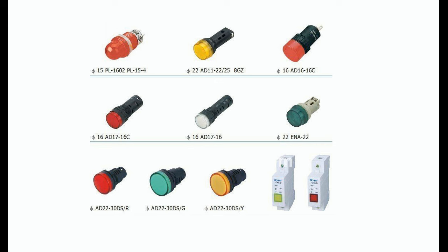The colors are usually red, green, or amber, but other colors are also available. Red lamps are reserved for safety critical indicators: power is on, the machine is running, an access panel is open, or that a fault has occurred. Green usually indicates safe conditions: power to the motor is off, brakes are on, etc. Amber indicates conditions that are important but not dangerous: fluid getting low, machine paused, machine warming up, etc.